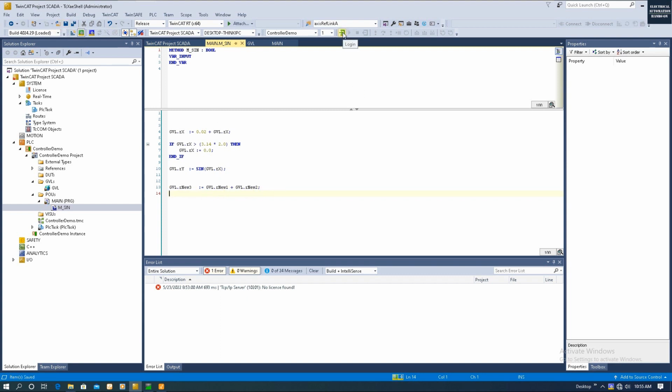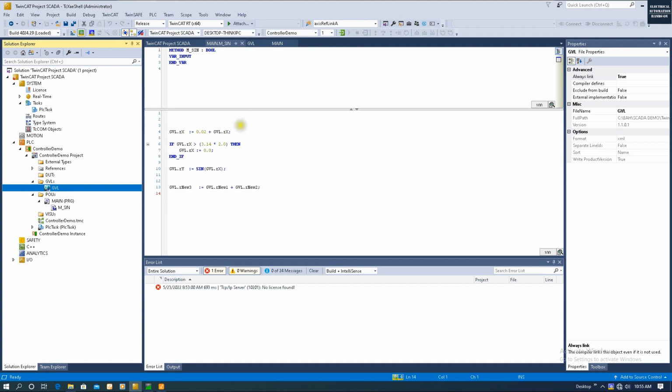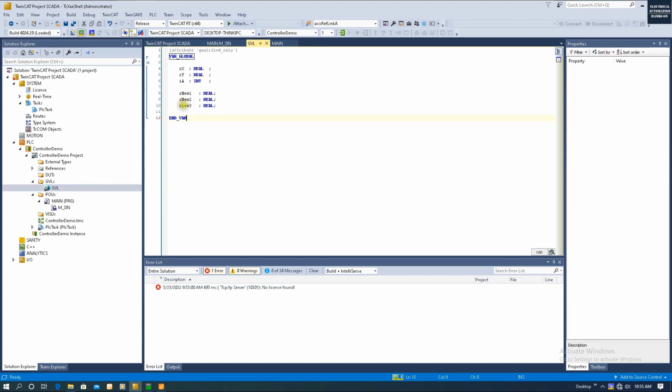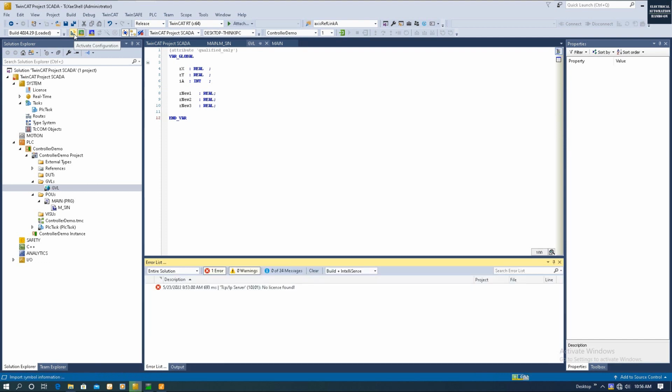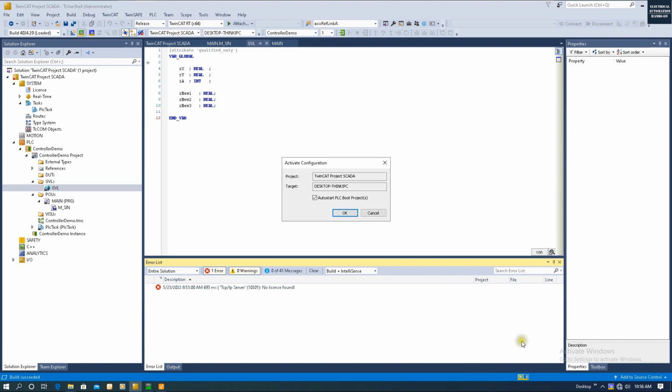And here, if we click this login, that's not enough, because the OPC UA, that PLC1 bridge, doesn't know that in this variable list we got this update already. We got these newly added variables already. So we need to tell the system that we have added 3 variables. Then the best and easiest way is that we can build a project and activate this configuration. When we activate this configuration, the controller will restart.